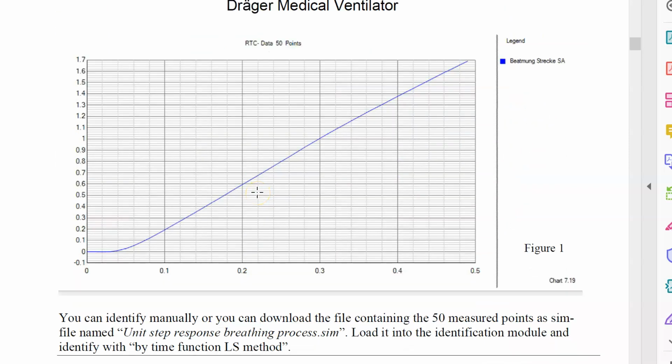you can see the diagram of a measured step response. We have done the job of measurement of the step response. So you see here is the time 0. Here the motor voltage is switched on with a small delay. Then you see a following ramp, and this ramp indicates that our process is an integrating process.